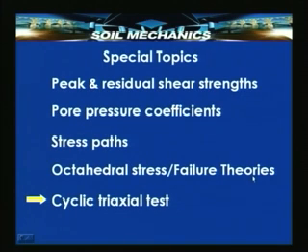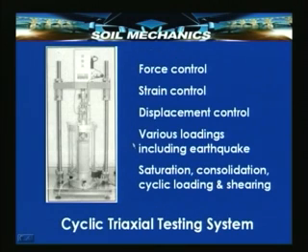Now, lastly we come to the test called cyclic triaxial test, about which I mentioned some time back, which is a very useful triaxial test and is a very innovative, relatively recent development and completely digital usually, and is of interest to know. Here is a simple illustration of a cyclic triaxial equipment. This has the facility to apply cyclic loading, and that is why it is called cyclic triaxial test. It is a conventional triaxial test, except that the load that can be applied can be cycled.